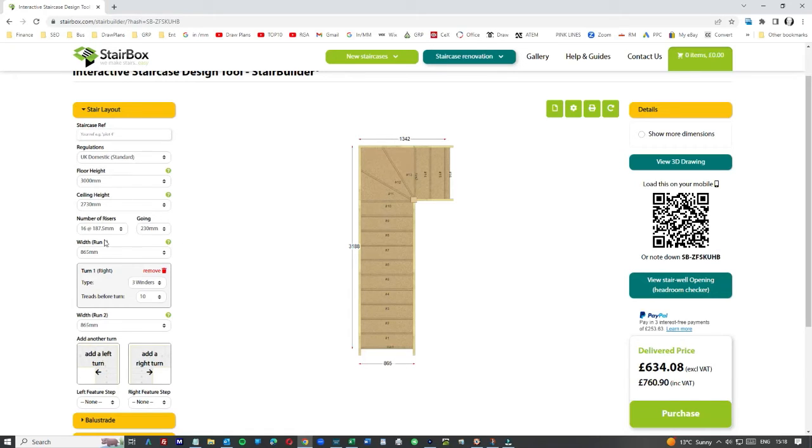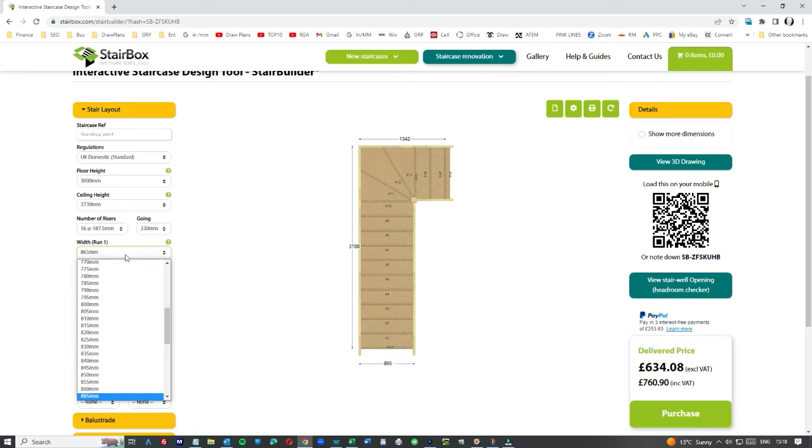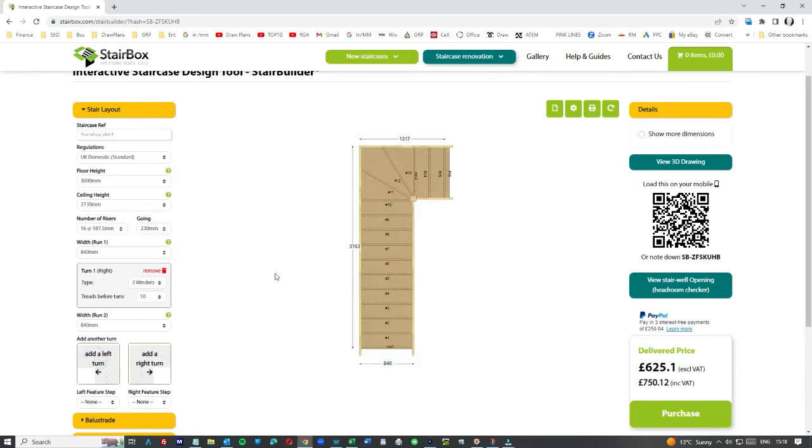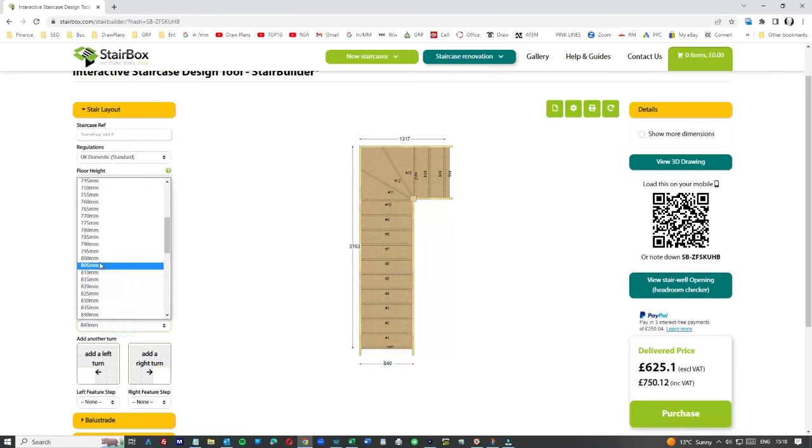Well, you can change the width of the staircase if you need to, because the width here is going to impact on this width. So if I change, let's assume the staircase here, if I want to make this a little shorter, 3188, I could try. So let's see, 3188, let's see if it changes. You see it does, because this changes. It's now reduced.